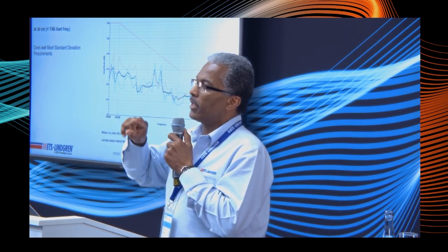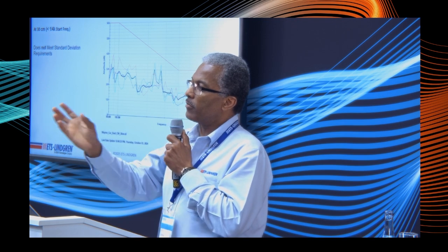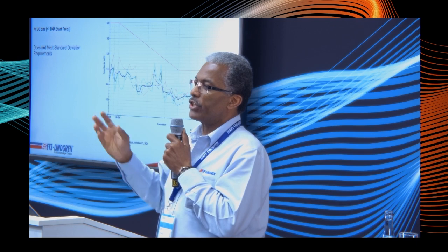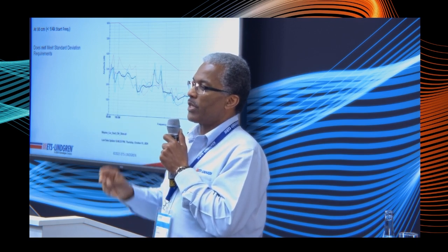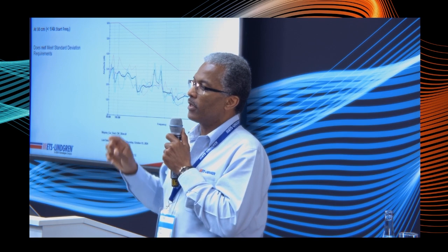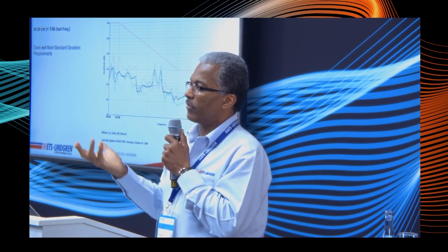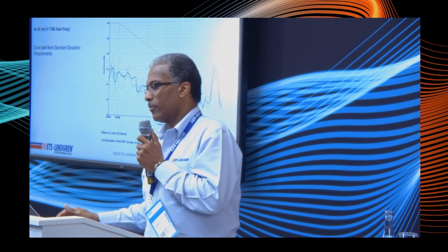As long as you have the same rotation of the stirrer, you have the same variation of the field or the modes within that cavity; that stays the same. All we're doing is changing the number of times we sample that field. If we take one sample, we get one number. If we take 100 samples, we get a much greater chance of measuring what the peak is in that environment. But the environment itself hasn't changed. Of course, we want to collect many samples because more samples mean less statistical uncertainty, but the samples need to be statistically uncorrelated, or independent of each other. If you have just one stirrer and rotate it 360 degrees, after this you will get more or less the very same samples again.